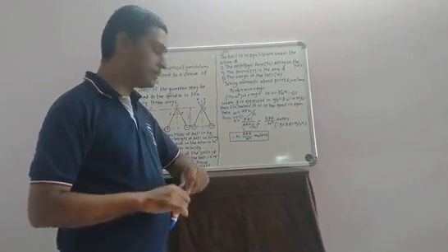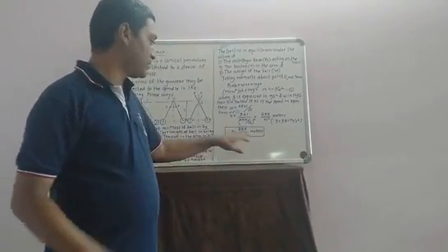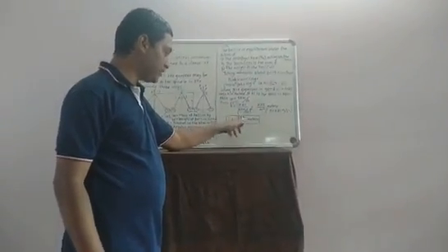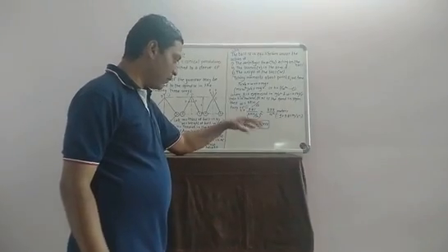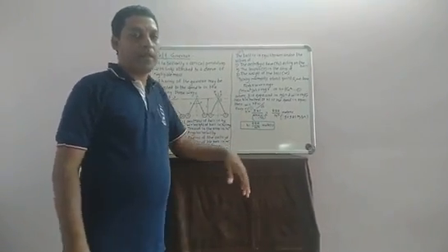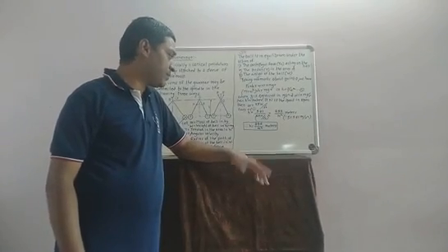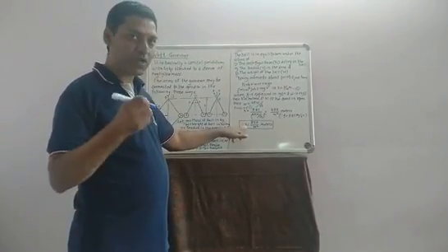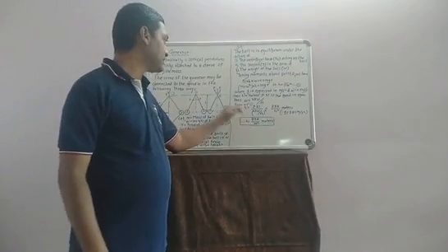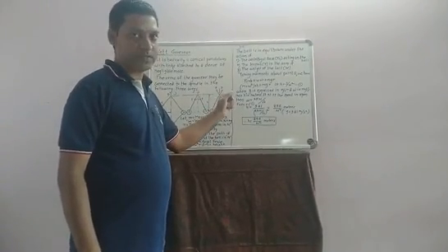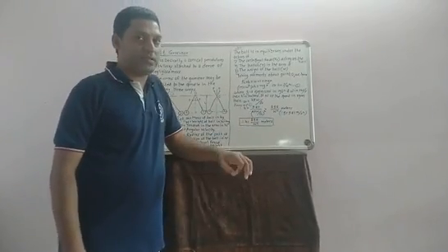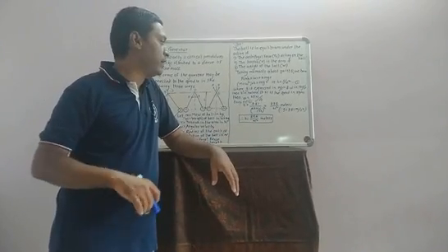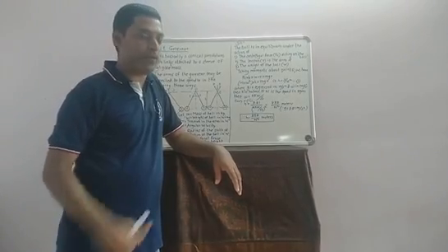In this case, if you look at n, which is in the denominator and squared, whenever the speed of the engine increases, the height automatically decreases. So for a small change in speed, this governor does not respond. Basically this works very well for low speeds, might be in a range of 60 to 80 rpm.